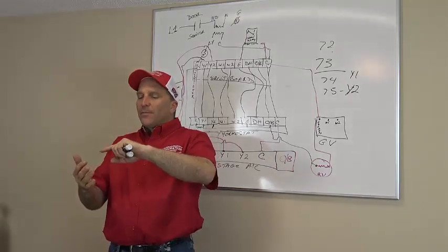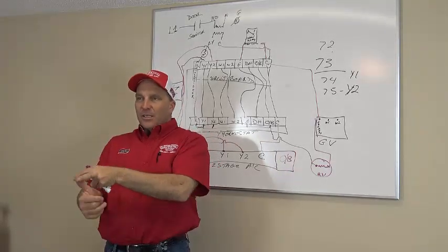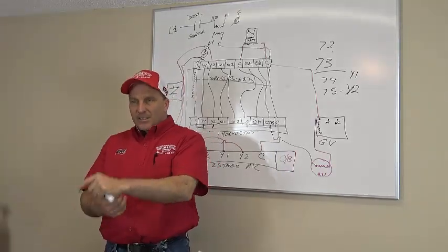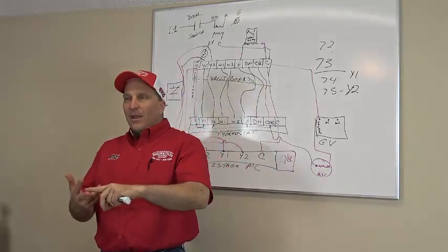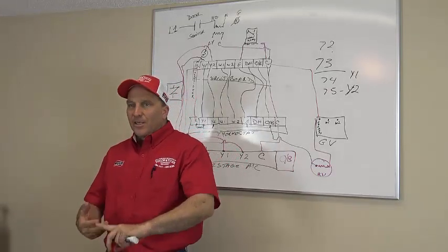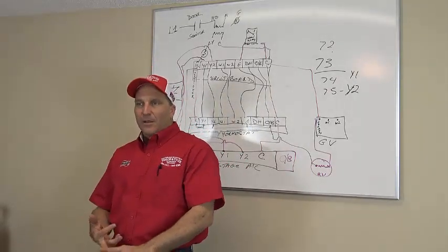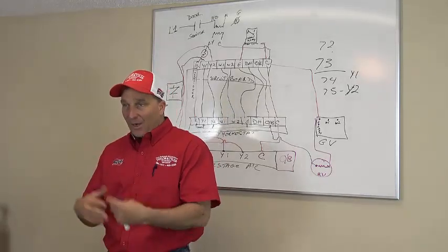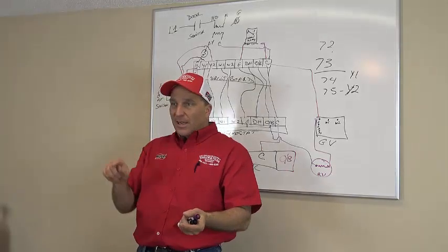I want you to be single-stage air conditioned, two-stage cool. Two-stage air conditioned, single-stage cool. Single-stage cooling, two-stage heating. I want you to be a heat pump, single-stage, a heat pump, two-stage, a dual fuel system, three-stage. I got to tell that thermostat what I want it to be. And it's 1 through 6 or 7 settings.